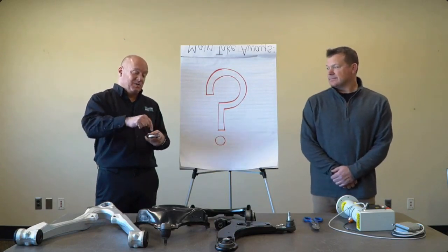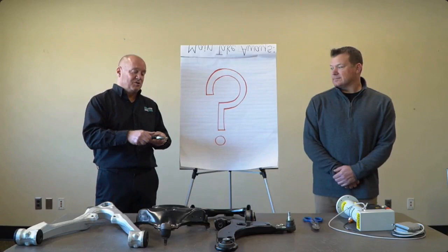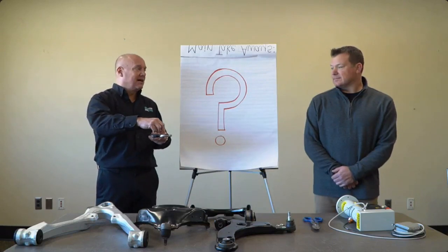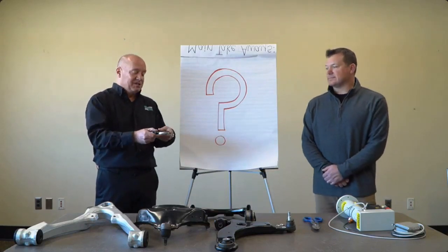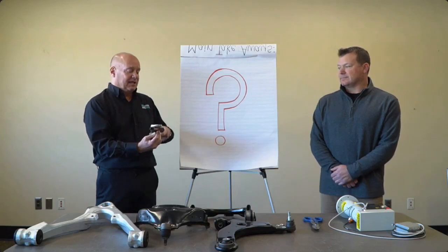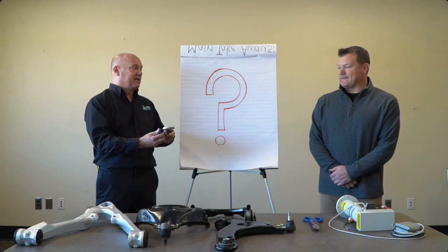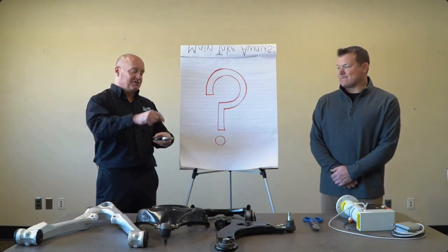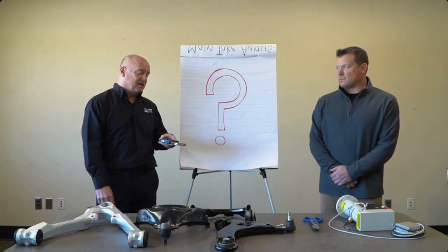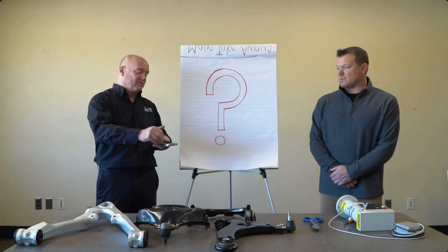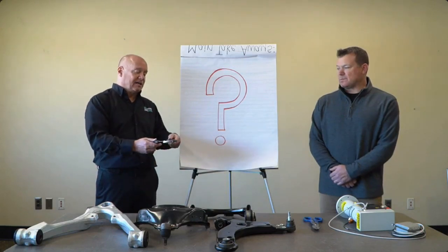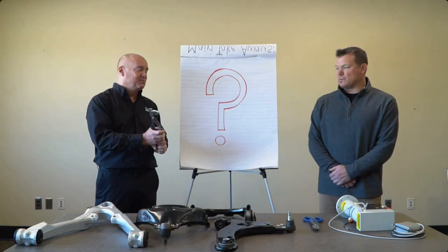This one, because we're measuring the function, it's not so critical as far as measuring microns or dimensionally, but you still have to hold it properly and be able to actuate it properly, because you're exercising the part depending on how you're cold heading or orbit forming the head. So yes, it really is part dependent.